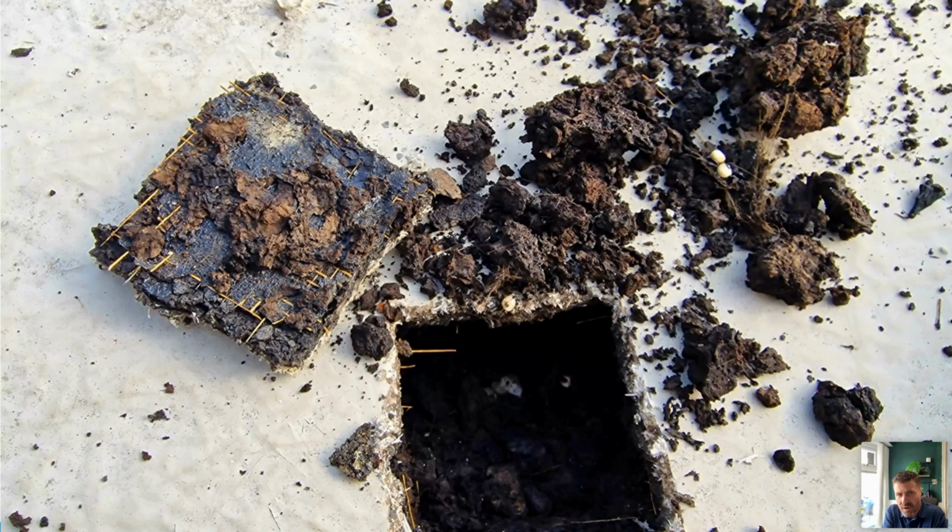You could also cut cork to any profile as well, so it was really handy back in the days when I used to design tapered insulation systems. Really handy to use cork sometimes where a slight fall was needed, or where more of a fall was needed as well, because like I say, cork could be used in those instances. It was a really kind of diverse product.